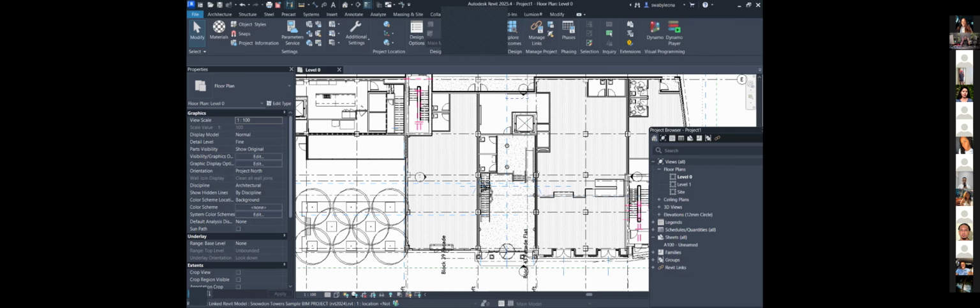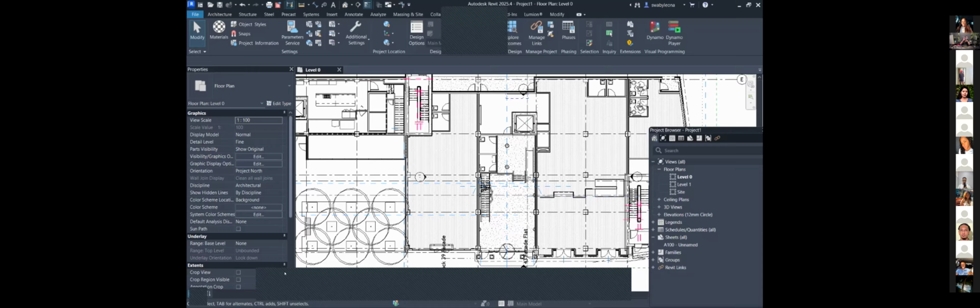Imagine one person working on the building, the common area, and the site plan, while somebody else works on one unit, which is linked into the model and multiplied 100 times. It's the same unit. That is one major feature of linking: once you have repeated elements, it gives the ability for collaboration and also to work efficiently.